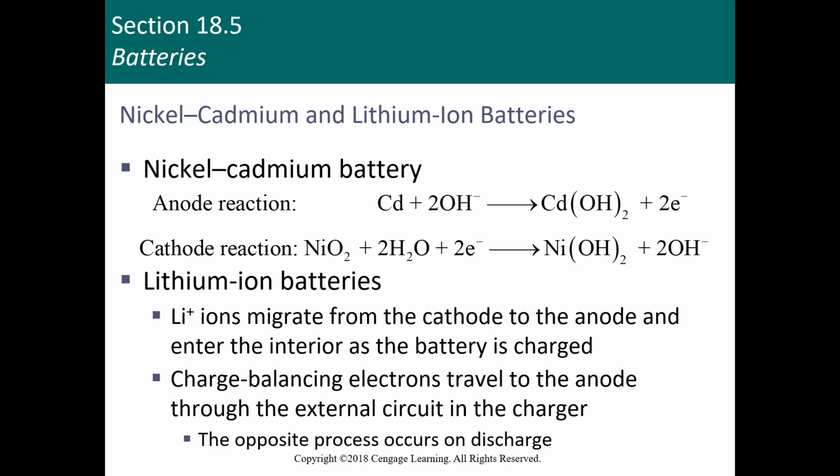And so some of the things that I can tell you that might help you in life is, don't let a lithium-ion battery get hot, especially if you're charging it. So if you charge a lithium-ion battery and it is warm, hot, especially don't let it actually get hot. So if you're charging it, do not leave it under a window or next to a fire or any of these things. Lithium-ion batteries, if they are hot while you're recharging it, you will make lithium crystals.